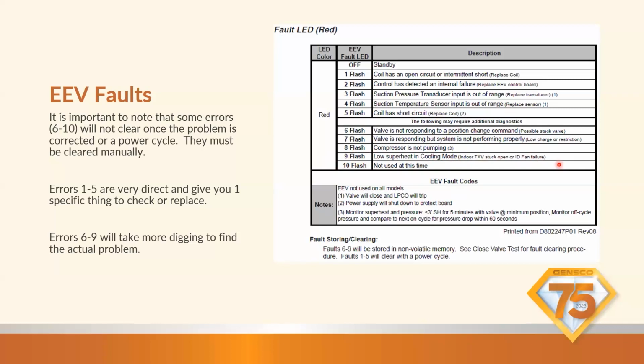That could be something where you had a bad EEV on your TAM9 on an indoor unit, and they got that fixed, and now the outdoor unit's got an error code. Well, you fixed the problem, but we still have to manually clear that.